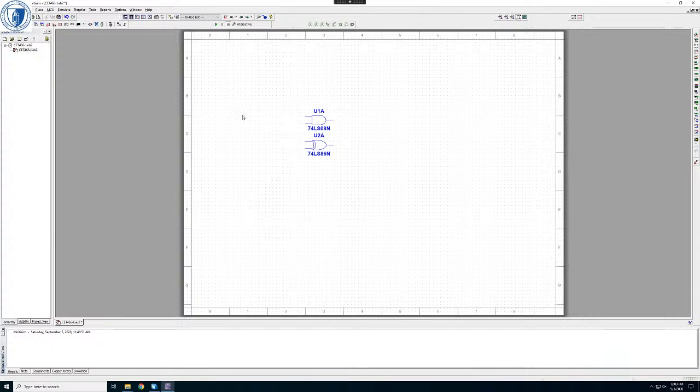Now, what we need next is we need to have inputs. And there's a couple of ways we could do inputs. One way, because there's two inputs and we want to exercise all possible values of the input, would be to have a 2-bit counter and have the counter go 00, 01, 10, 11, continually.